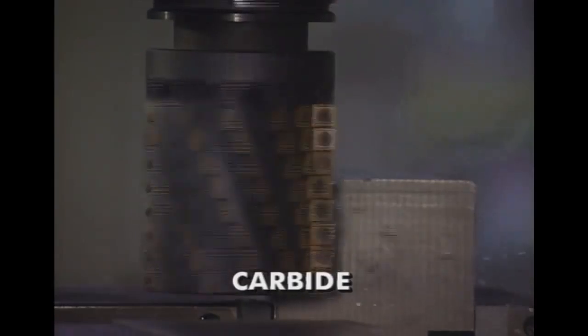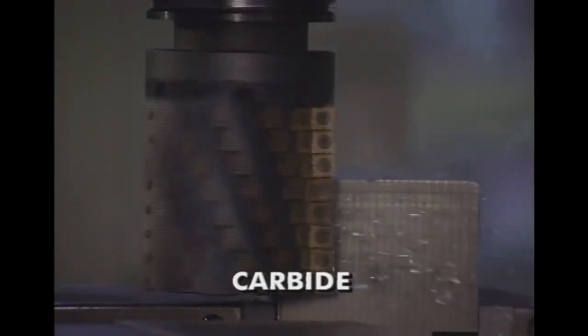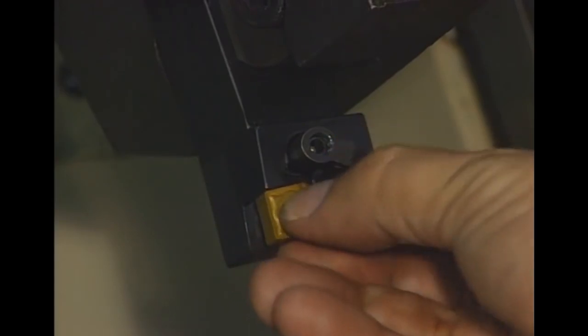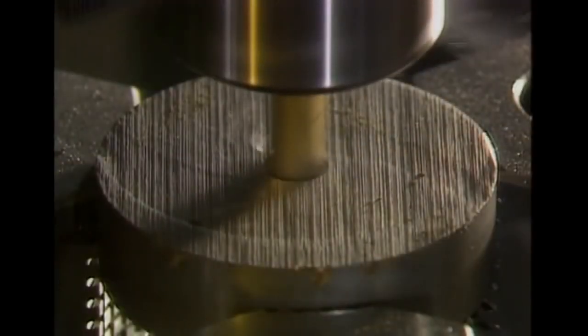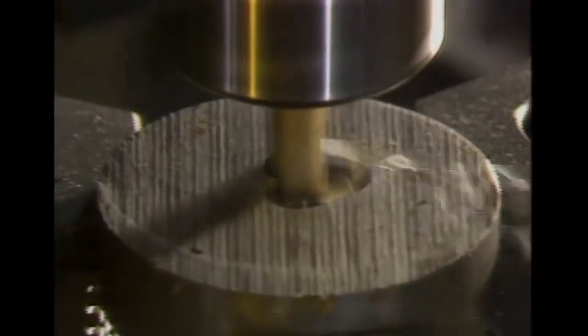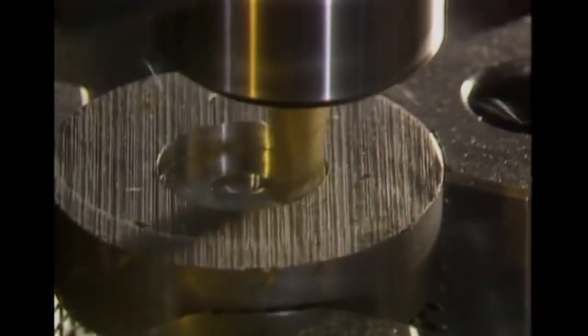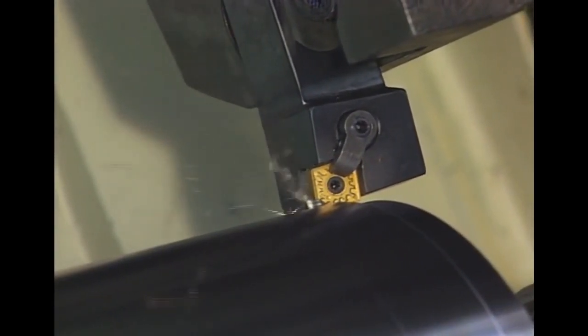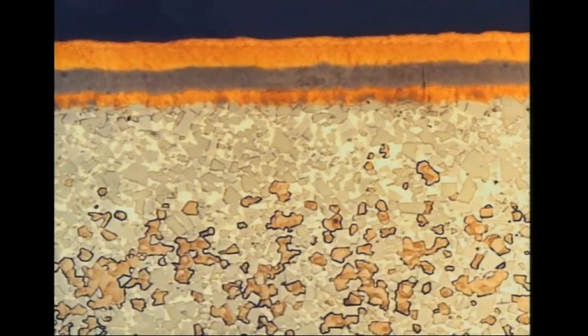Carbide tools, particularly coated carbides, are today's most common cutting tool material. There are a great variety of carbide compositions and coating types. Carbide tools may be indexable inserts or solid round tools such as small diameter end mills or drills. Coated carbide inserts are the first tool material to consider for most production operations. Most insert coatings have multiple layers to protect the tool against abrasion and chemical wear.